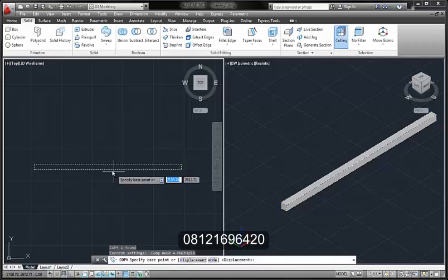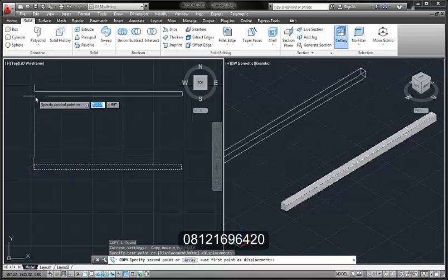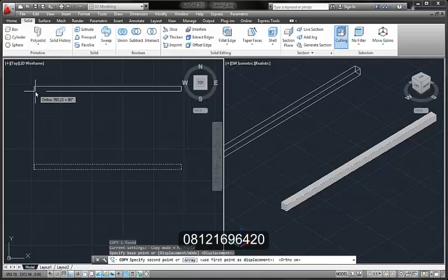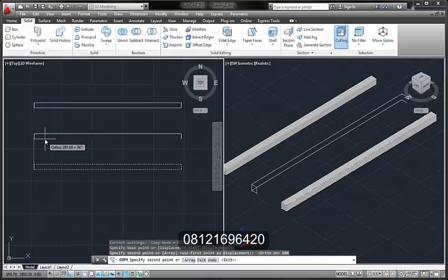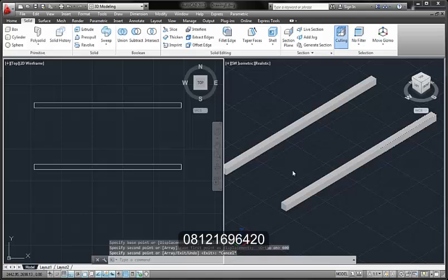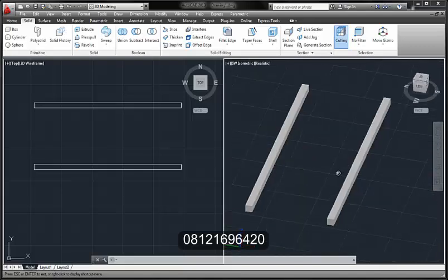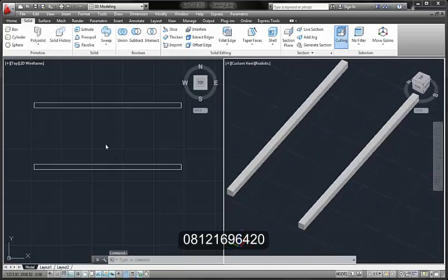I want to cover a distance of about 600 mm, possibly from inside here. So I'll click here, and I'll turn on my F8 to have a vertical straight line. Then I type 600, and then press escape. So I have the two bays right here, and then I'm good to go. I can orbit my two bays. It's a very good result.